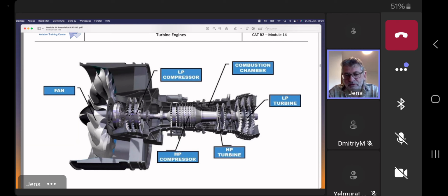And if the dynamic pressure goes down, the static pressure goes up. It is different in the convergent shape, where we accelerate. So the kinetic energy, the dynamic pressure will be enhanced. And if you enhance the dynamic pressure, the static pressure goes down. But this only is valid for speeds below the speed of sound. So in case the air itself should exceed the speed of sound, it goes 180 degrees opposite.